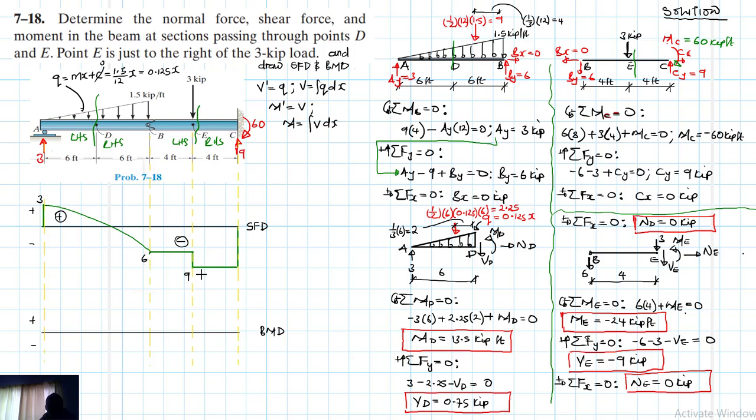All right. But before we do that, we need to find the function that governs the shear, right? So that we integrate it from 0 to 12, and we are going to find moment there equal to 0. So our shear, in the region AB, our shear function, which is a function of x. We are just going to put it like x, and x varies from 0 to 12.